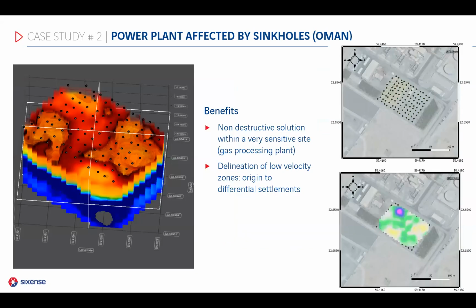So this is the final model we obtained using these 100 geophones. The geological model, geotechnical model is quite simple, but we observe two different layers. The first layer of low geotechnical properties corresponds to the backfill materials and superficial deposits. And in blue here with high velocity materials, we have the bedrock, or what is interpreted as the bedrock, at least stiff materials, competent materials. So globally speaking,